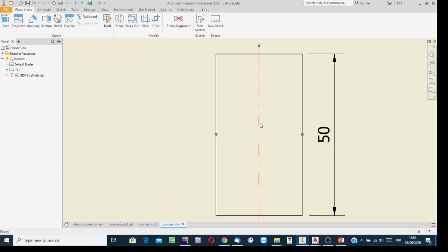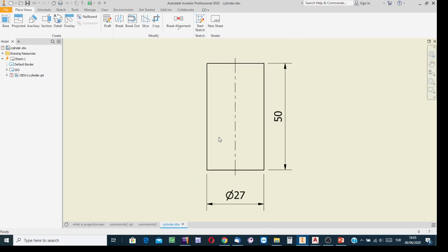You have already learned the meaning of this line. It says that it is an axis of symmetry. On the views of which features, which objects, do we show such an axis? You know the answer. If the image is the lateral side view of a revolved object, we show the axis. It is called the longitudinal axis. The longitudinal axis is shining to say that it is the image of a revolved object. The revolved object is a cylinder, a cone, or a truncated cone.